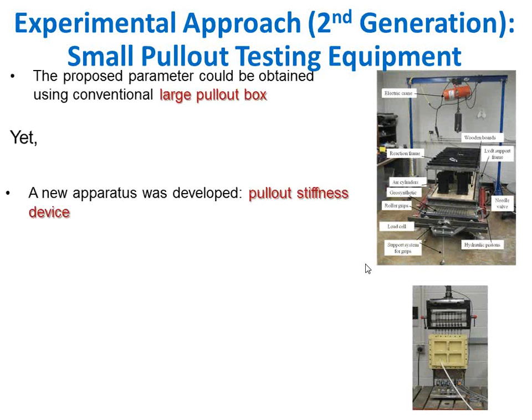Are you familiar with the tensile test on geosynthetics? Why the tensile test? Same frame. Same clamps. This is what is called the roller grip. If we do a tensile test, here's a clamp. This is a grid. Here you would have another clamp, you apply a tensile load, you do a tensile test. Here what we're going to do is replace this lower clamp by a mini pull-out box. We sandwich the second end of the reinforcement. And it's still a tensile test, which a pull-out test is a tensile test.